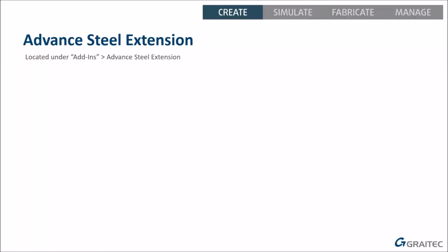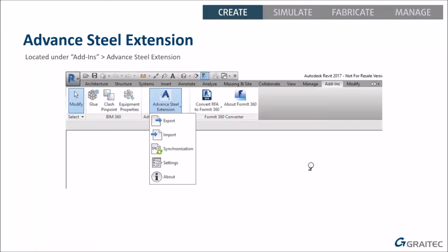After 2019, it's available in your desktop app, or it's available through your Autodesk account. So if you go to manage.autodesk.com, you'll see it in there. Once you've installed it in Revit, it's under Add-ins under the Advanced Steel extension.